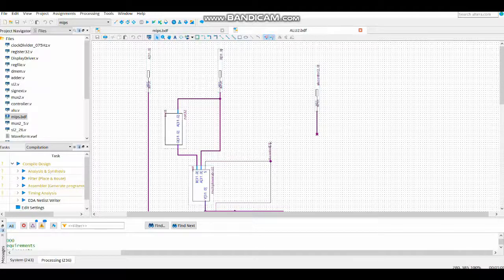The general strategy: different circuits combined by a multiplexer, where the select becomes the function select for the ALU. Invert the B input for subtraction, feed the output of the high order bit of the adder to the low order bit for set on less than operation, and use an OR gate on the ALU output for the equal test. So what I explained just now is basically how the ALU operates.